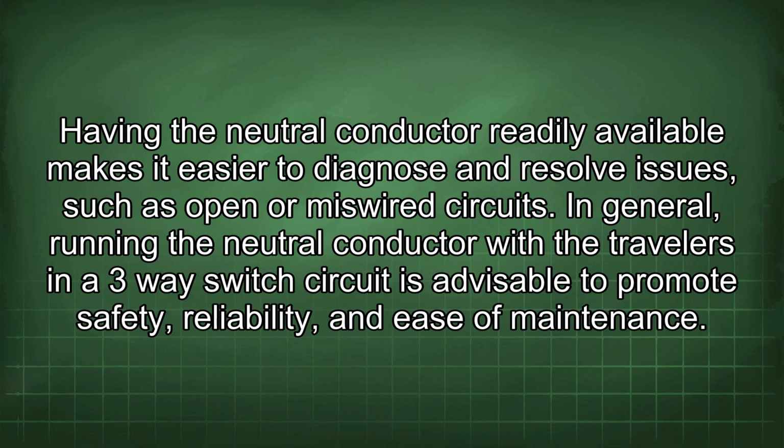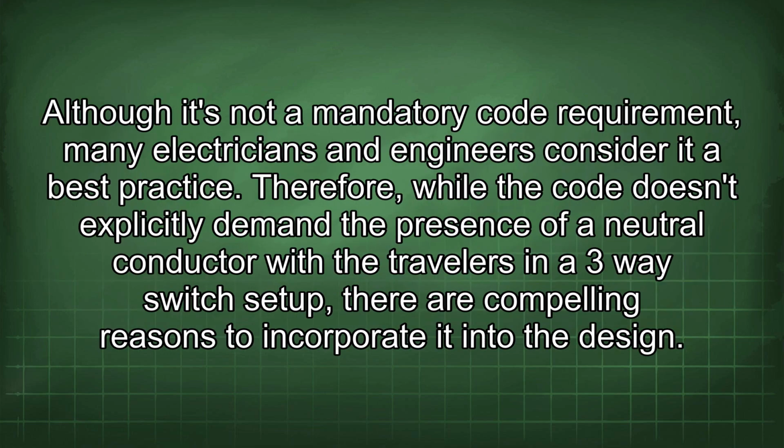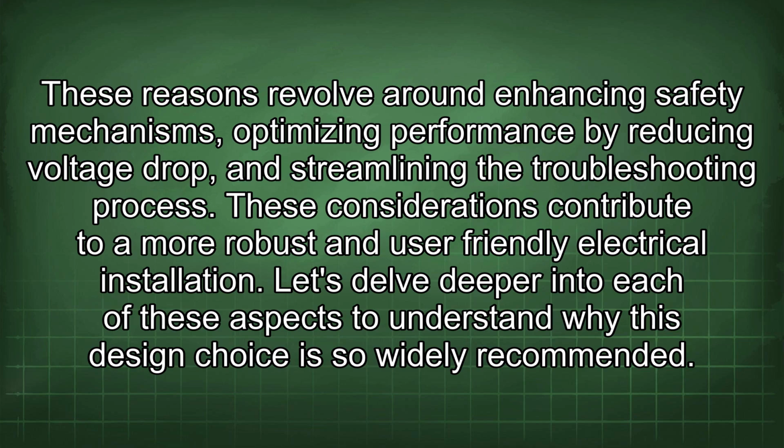In general, running the neutral conductor with the travelers in a three-way switch circuit is advisable to promote safety, reliability, and ease of maintenance. Although it's not a mandatory code requirement, many electricians and engineers consider it a best practice. Therefore, while the code doesn't explicitly demand the presence of a neutral conductor with the travelers in a three-way switch setup, there are compelling reasons to incorporate it into the design. These reasons revolve around enhancing safety mechanisms, optimizing performance by reducing voltage drop, and streamlining the troubleshooting process. These considerations contribute to a more robust and user-friendly electrical installation.